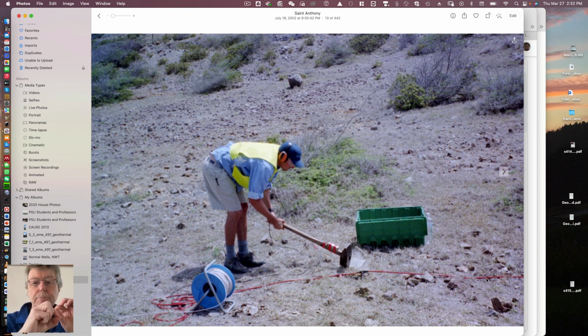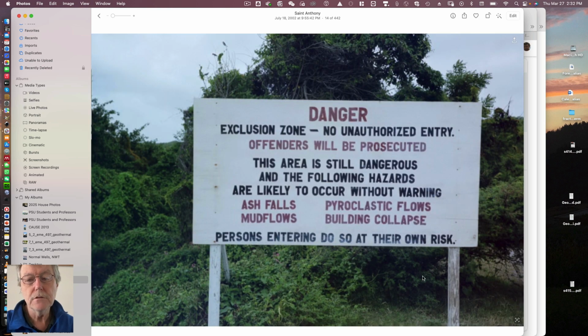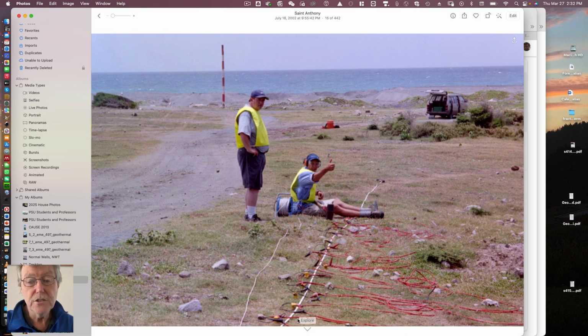So this would be a string of geophones attached to a single trunk wire. They're attached with crocodile clips onto the trunk, and the energy source in this particular case is a sledgehammer with an electrical cable to the sledgehammer and a plate. That plate is attached to a battery, so that when you close the circuit, it immediately gets the timing of the impulse, which is then picked up on the individual geophones in the surface. So the geophones would be laid out along a length, connected along a trunk line to gather all the acoustic signals, the first arrivals, and then that information would be